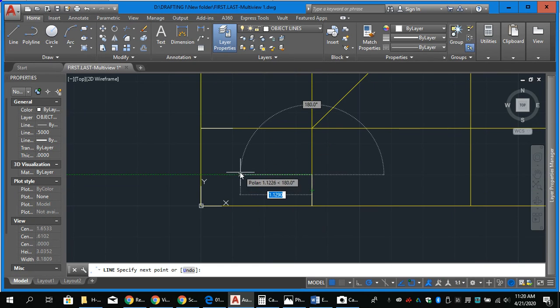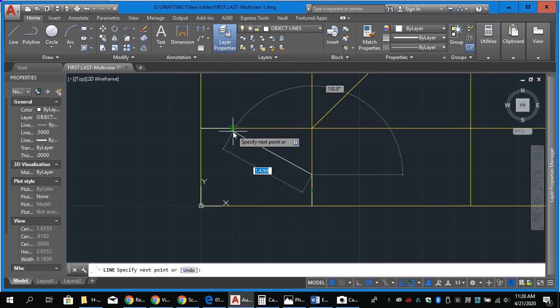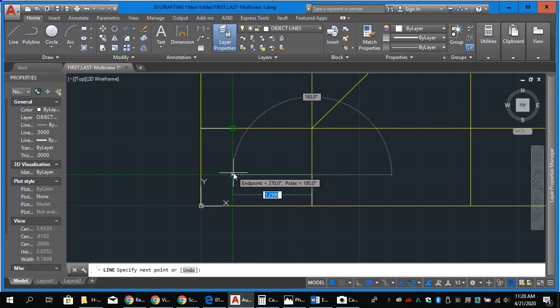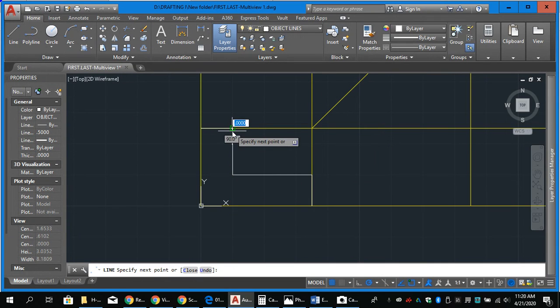So I'm going to drag over to the right, and I'm just going to come up and hover over the endpoint of the line that I drew up top. Don't click on it because we don't want to draw a line there, but then I'm going to drag down, and it will accurately snap or remember that point for me, and I can then snap and click on the exact point where those would intersect. Then draw straight up. Now spacebar again. The next thing I need to do is draw this bottom corner with lines and then spacebar. So I've got my L shape.